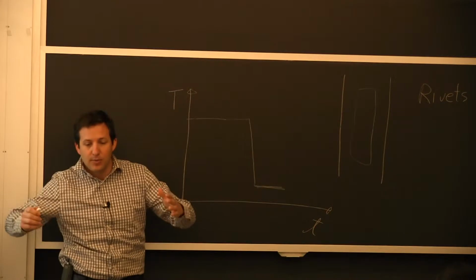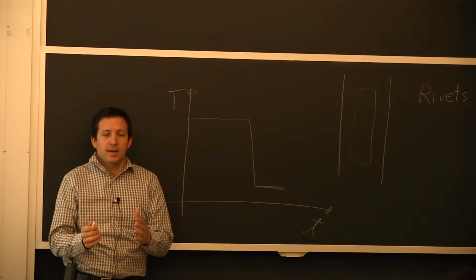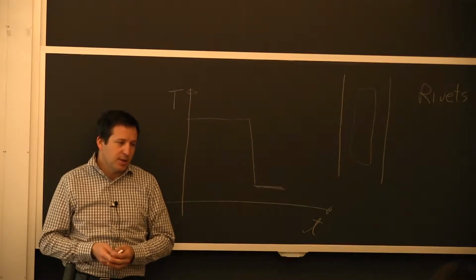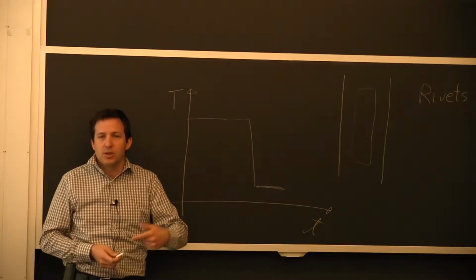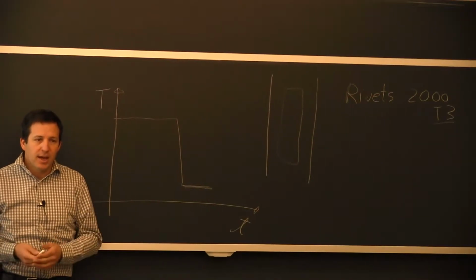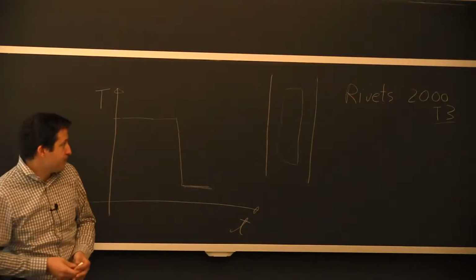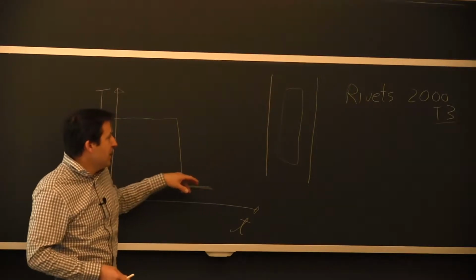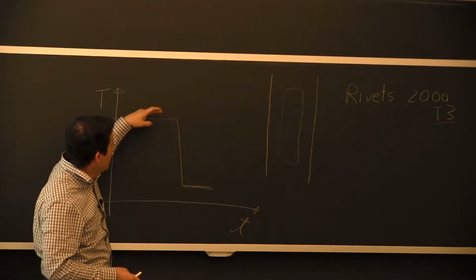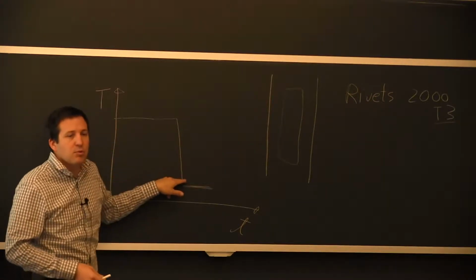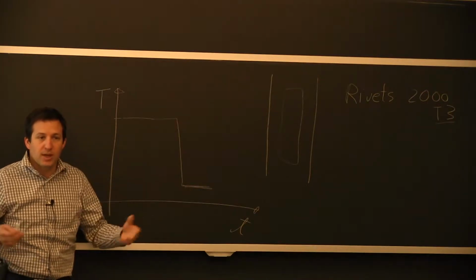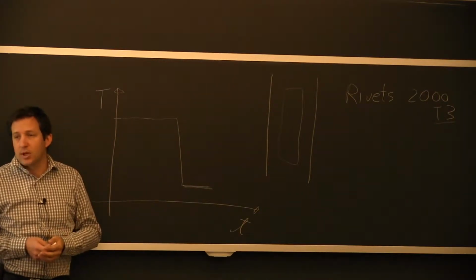And the fact of deforming the rivet to make the joint activates the formation of these precipitates. It accelerates it, and it's also changing how they form. So it's a good combination of design to say, I'm going to quench it, it's going to remain relatively soft, then I do my forming, and over time it gains strength.